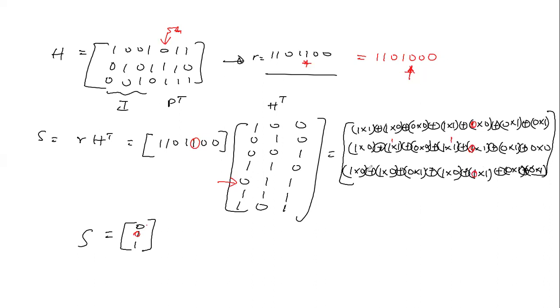So here is now, this is 0, this 0, this 0, this 0, this 0, this 0, 0. So everything has now reduced to 0, 0, 0. So the syndrome is now all zeros to tell us that this is the actual correct, originally transmitted bit sequence, okay? So you now see that with the syndrome, we are able to detect single bit errors for the Hamming